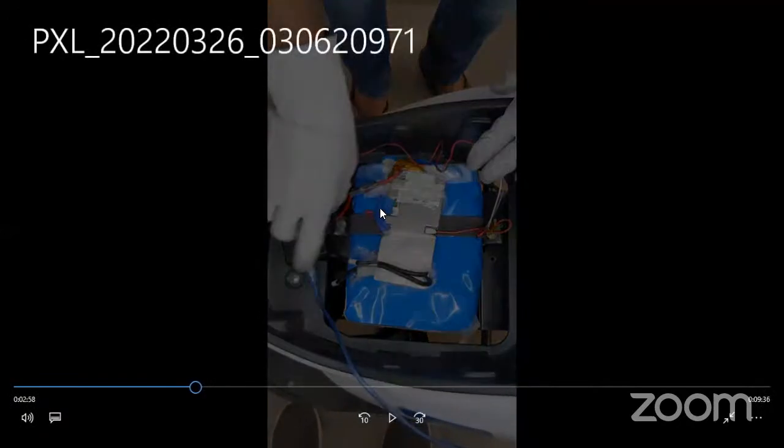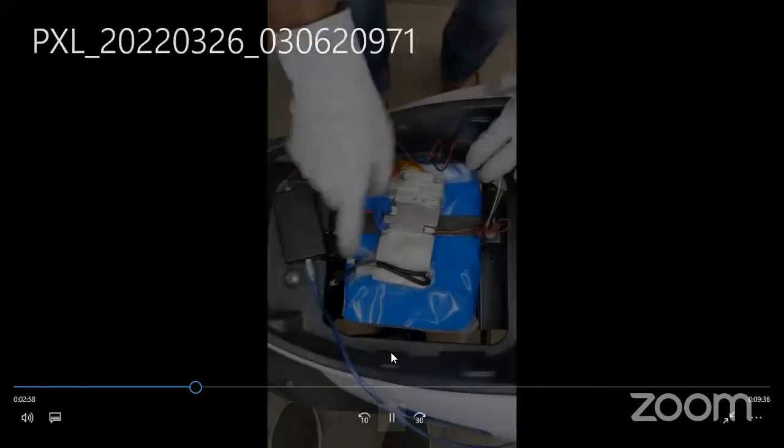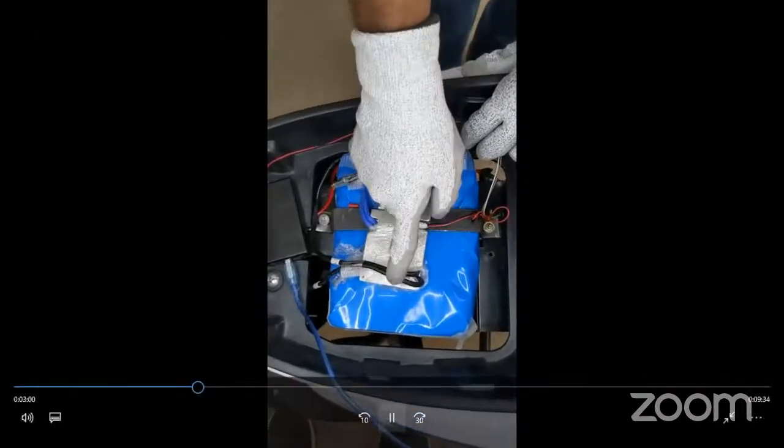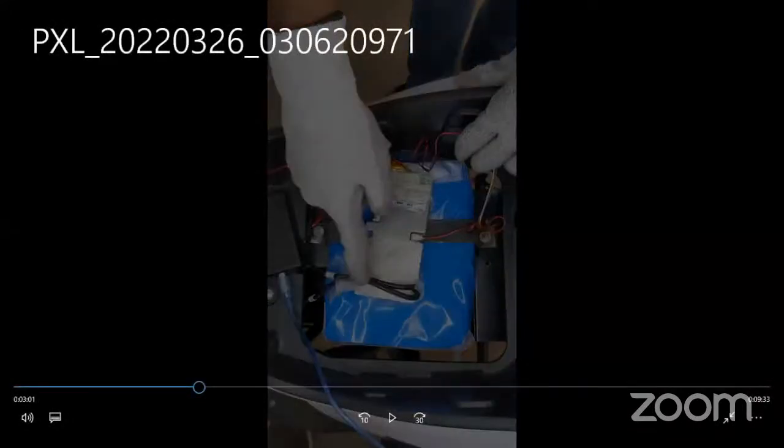Here you could see we have used two wires because the current was on a higher grade, above 30 amps, and these are 3C cells. It's up to 40 amps, sir. And we have separate wires for charging and discharging, right? This is again a 48-volt system for a low speed electric vehicle. You can see in the battery module again, we have one for charging.